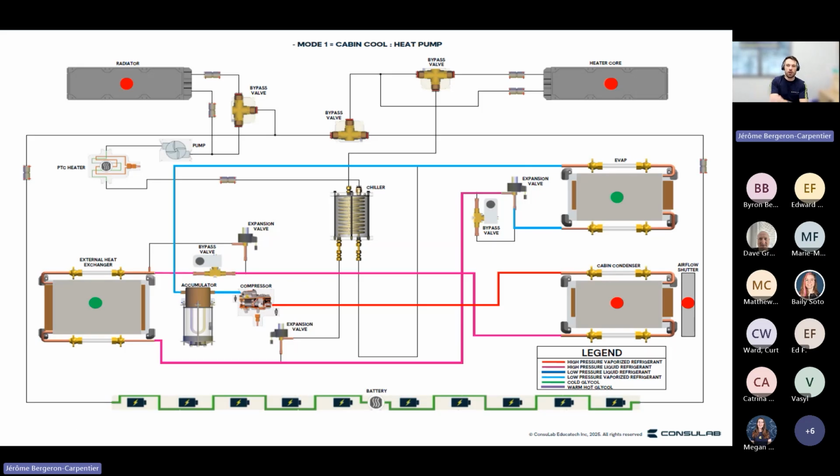So there's not going to be any airflow. The fans of that heat exchanger are going to be off. The airflow shutter is also going to be closed, to prevent any heat going inside the cabin. So there is no heat transfer in that heat exchanger in that mode. It's like having a long pipe. We're going to go here, bypass. We are not going to use that EEV, that TXV valve, that electronic expansion valve. We're just going to go bypass.